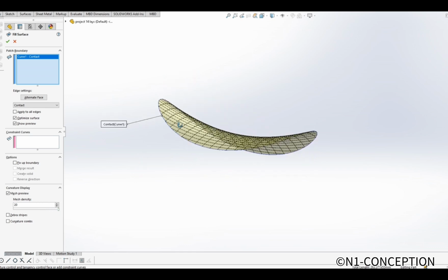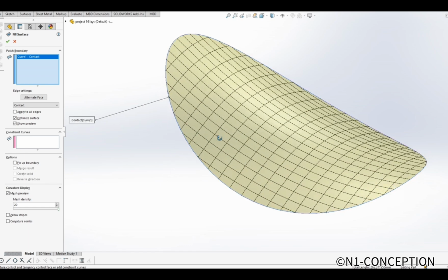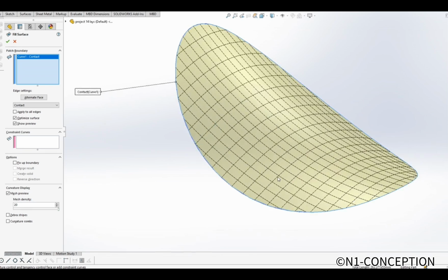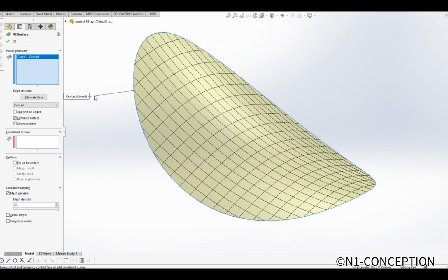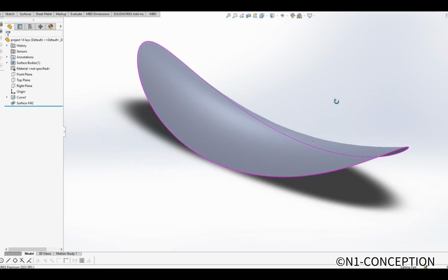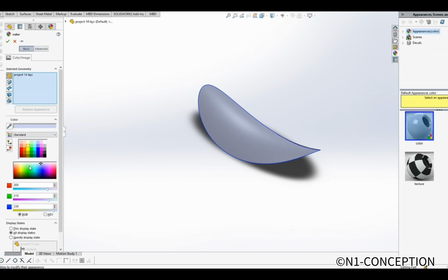A chip doesn't lie flat, it curves in one direction, and slightly bends in the other. To achieve this, I carefully adjusted the loft curves and spline handles. I also applied the flex tool in SolidWorks to give it that light twist in the middle. This step makes a huge difference, because without it, the chip would look like a flat biscuit instead of the famous Lay's crisp. By the end of this stage, the geometry was looking almost identical to the real snack.